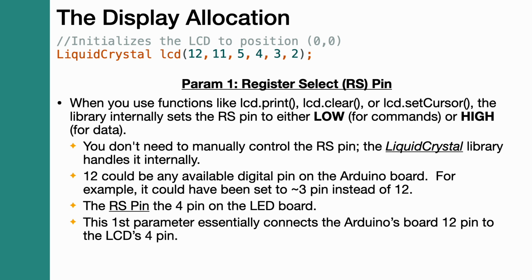Again, you don't have to do anything. You didn't see anything about RS pin high, low, 12 pin high, low. We didn't do any of that. Liquid Crystal Library took care of that for us, but this is what it's doing for you underneath. It's just telling the display to get prepared.